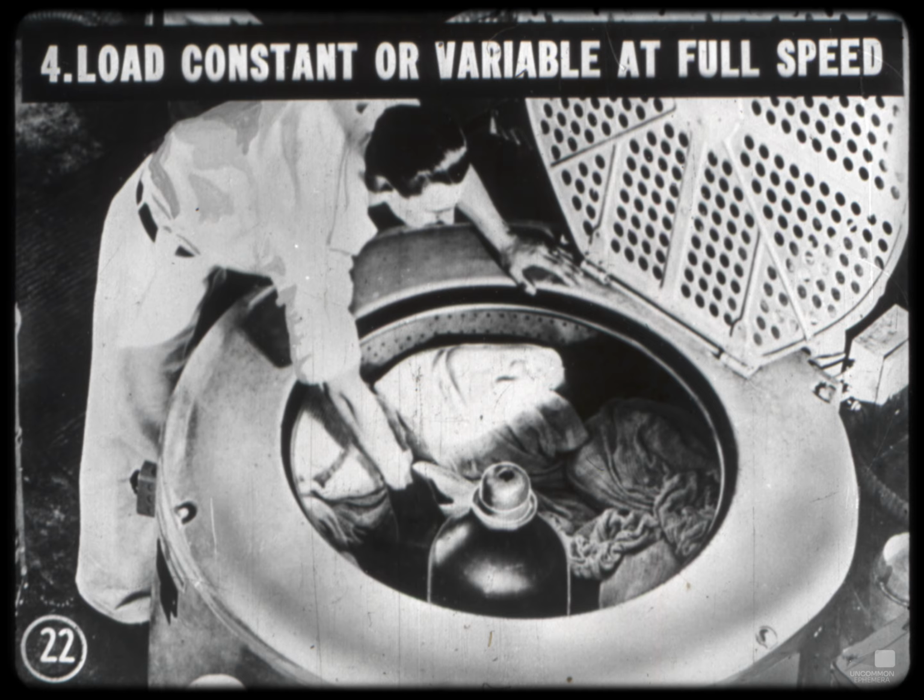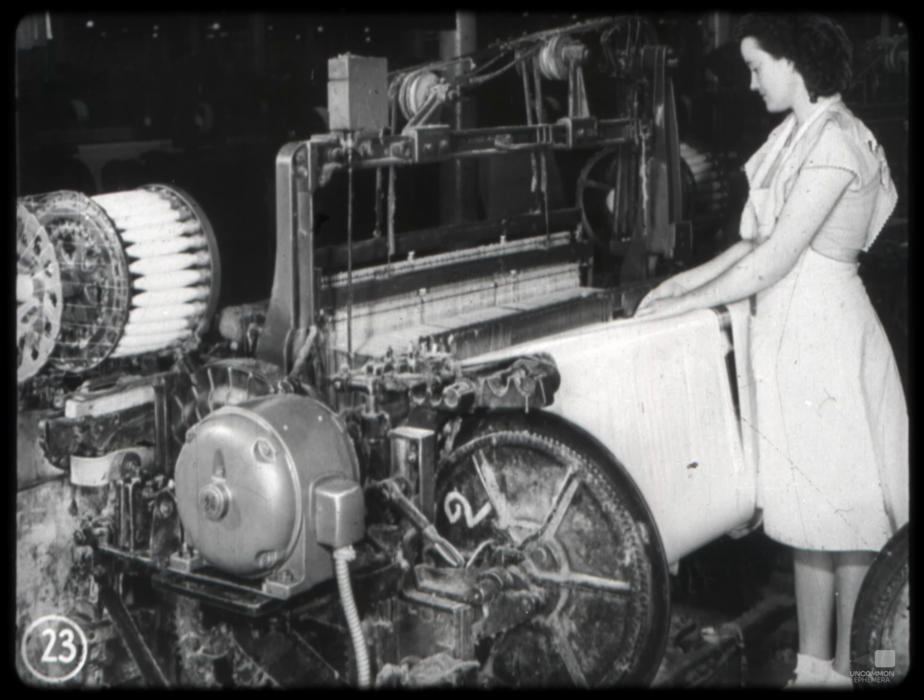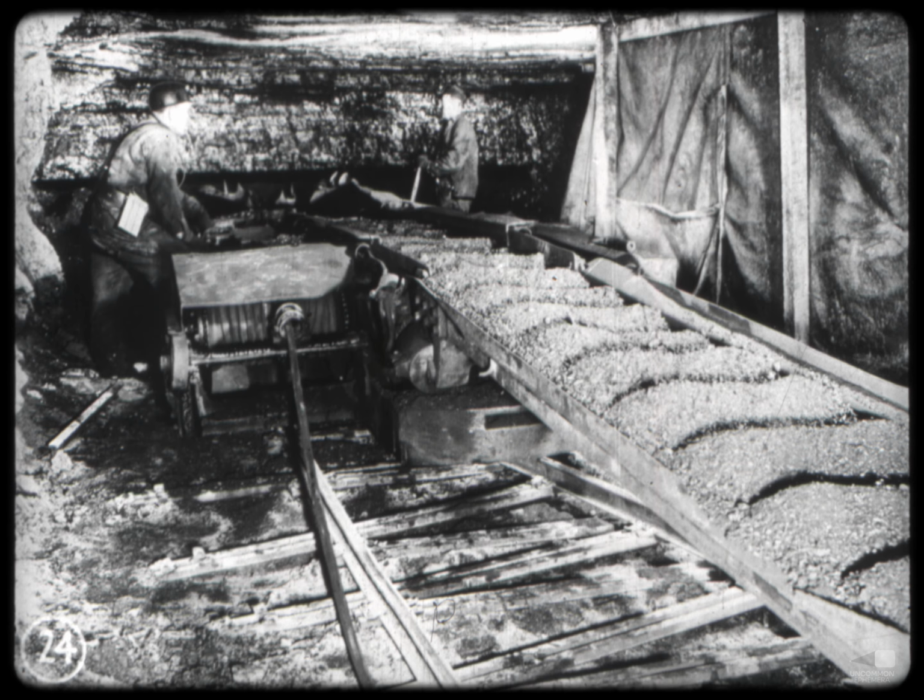After the machine's duty cycle has been determined, it's important to consider the product or process involved. On a textile loom such as this, a totally enclosed motor would be used because lint would soon clog up a motor with an ordinary open-type enclosure. It's important, too, to know if the motor will operate in a hazardous location, such as in this mine or in some refineries. Here, an explosion-proof enclosure is specified for safety's sake.